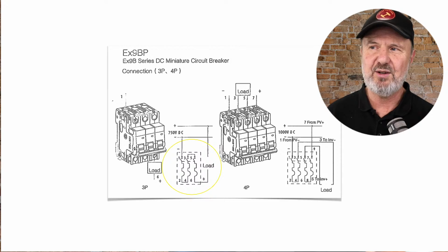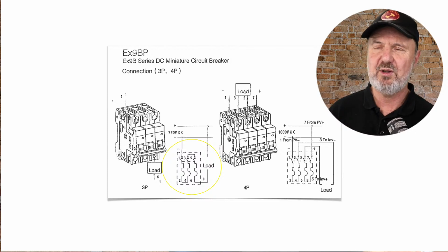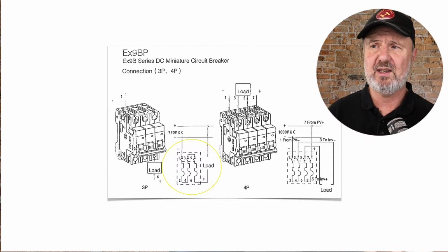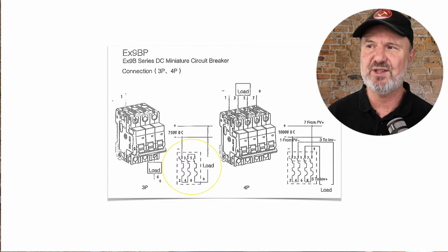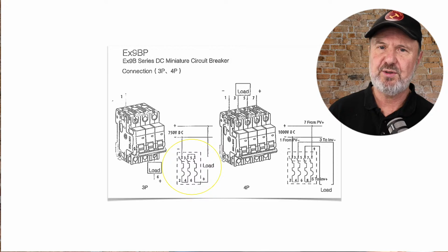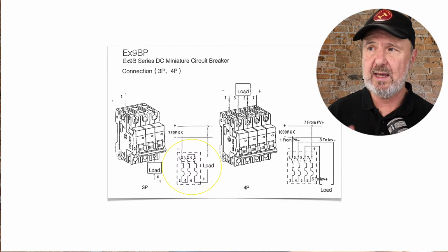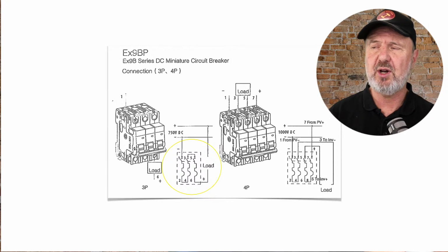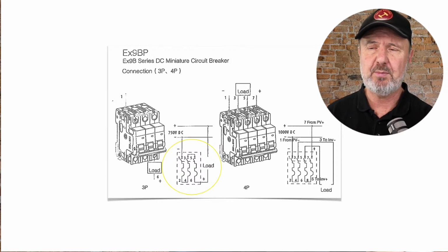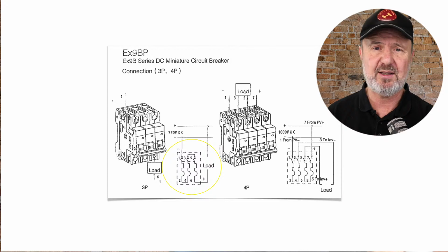So we actually don't have a double-pole isolation on both the positive and the negative. And that's common for systems where the negative conductor might be grounded, for instance, though it's very uncommon these days for grid connect systems to ground the negative conductor because of the topology of inverters. The picture on the right there is showing a 4-pole device, and 4 poles can be wired in different combinations of series and parallel for different outcomes.